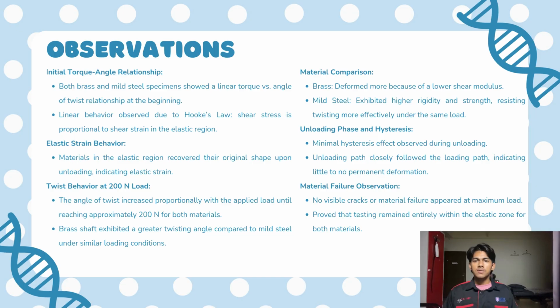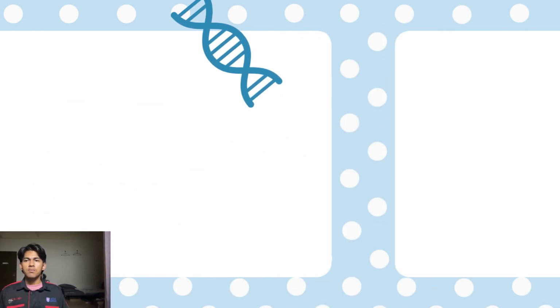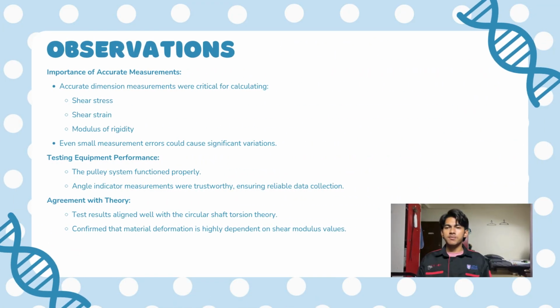The unloading path closely followed the loading path, indicating little to no permanent deformation. Sixth, material failure observation. No visible cracks or material failure appeared at maximum load, proof that testing remained entirely within the elastic zone for both materials. Seventh, importance of accurate measurements.